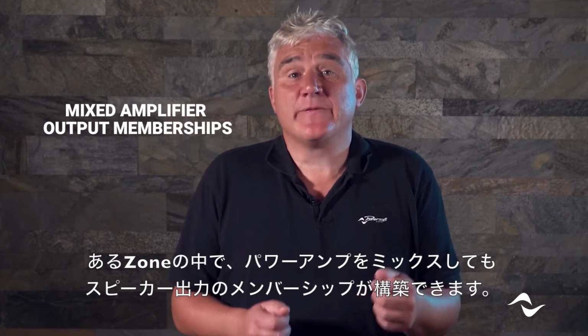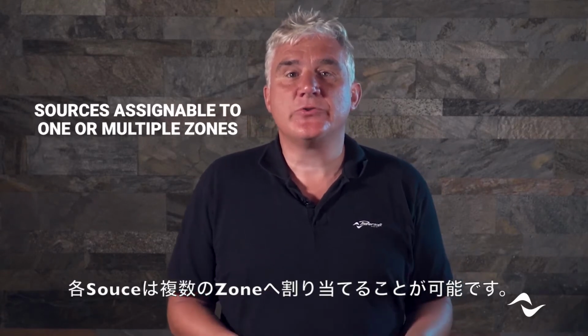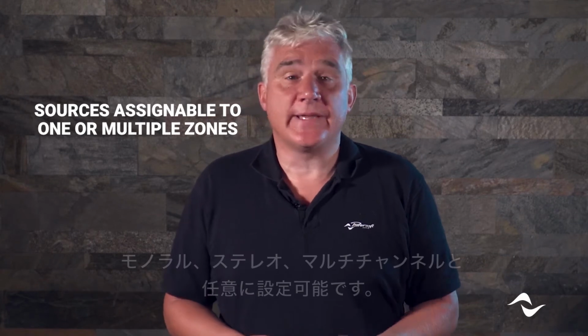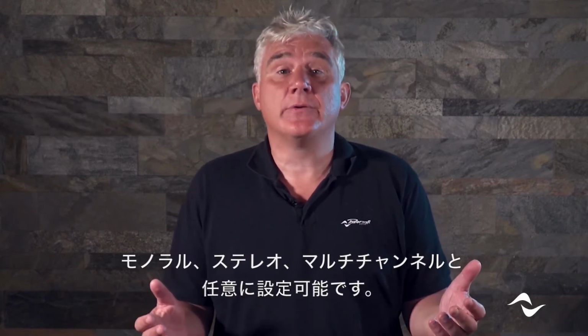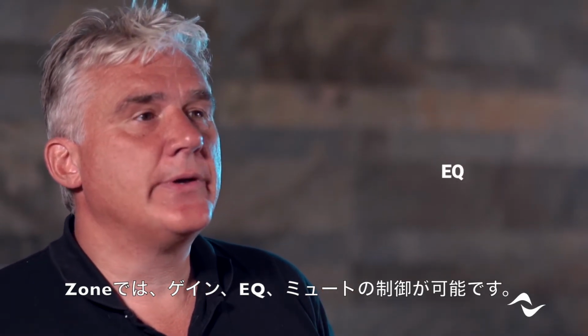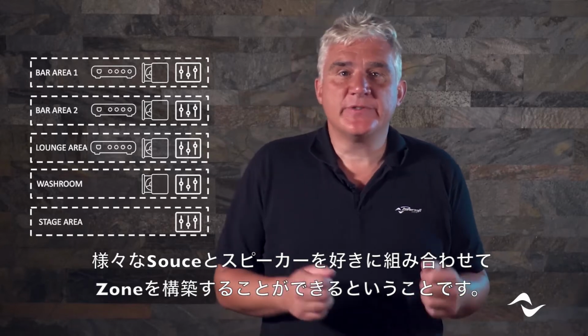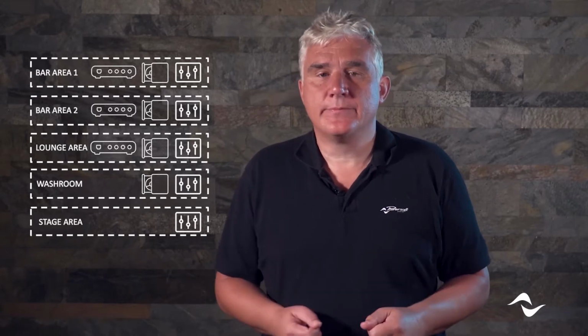We can take mixed amplifier outputs and make them members of one zone. And sources can be assigned to one or multiple zones. They can be mono, stereo, or multi-channel. So in the zone controls, we can control gain, EQ, and we can mute them. Meaning we can add and combine various inputs and speakers to a zone in our example.